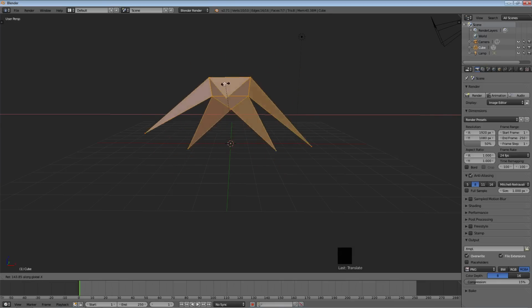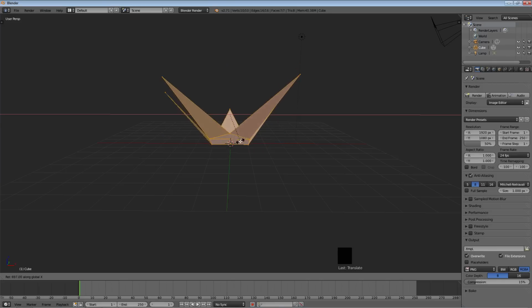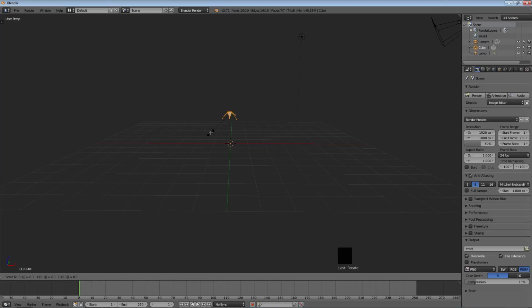So you can actually type in the numbers if you want while you're scaling, transforming, or rotating. I'm going to try 180 while I have this, and you'll see down in the bottom left corner of the 3D view window, it'll actually say what you typed to confirm. So 180 degrees, and I hit enter. And then I want to scale it down just to show you, and I'll type 0.1. I can hit backspace. 0.9, just to scale it slightly smaller. Hit enter.